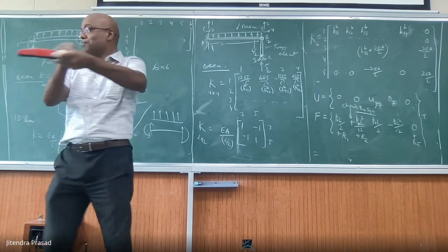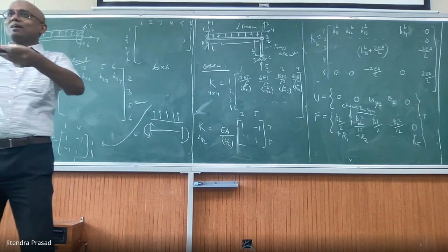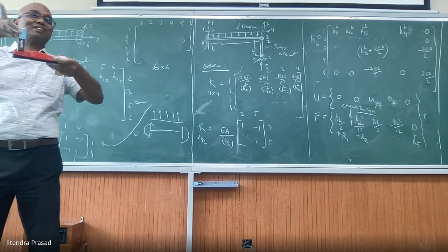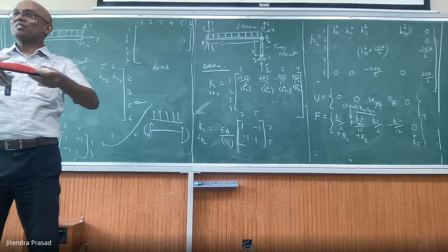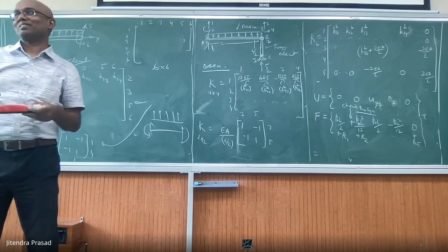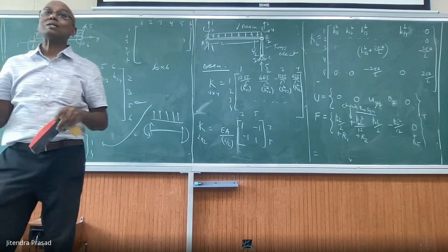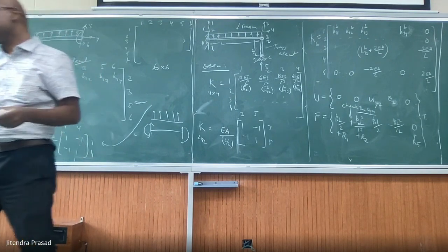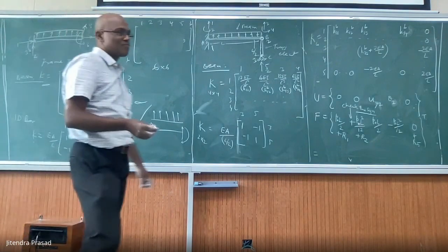You can take a 3D frame, so it goes from here to here. Let us say one more like this. You can apply some oblique force here. Automatically you will see that there will be a combined axial, torsion, and bending in all 3. Solve it. So the only thing is, how many degrees of freedom per node, all possibilities combined?